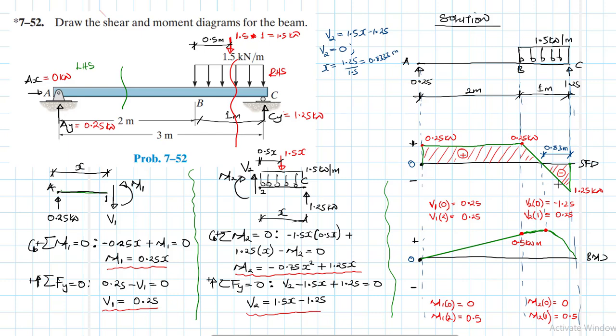So knowing that length, we know that the area under the shear diagram gives us the moment. This portion can give us the maximum, or this portion will give us the same value of maximum if we calculated the areas. We can use whichever portion, either on the left or on the right. I'm going to use this one on the right.